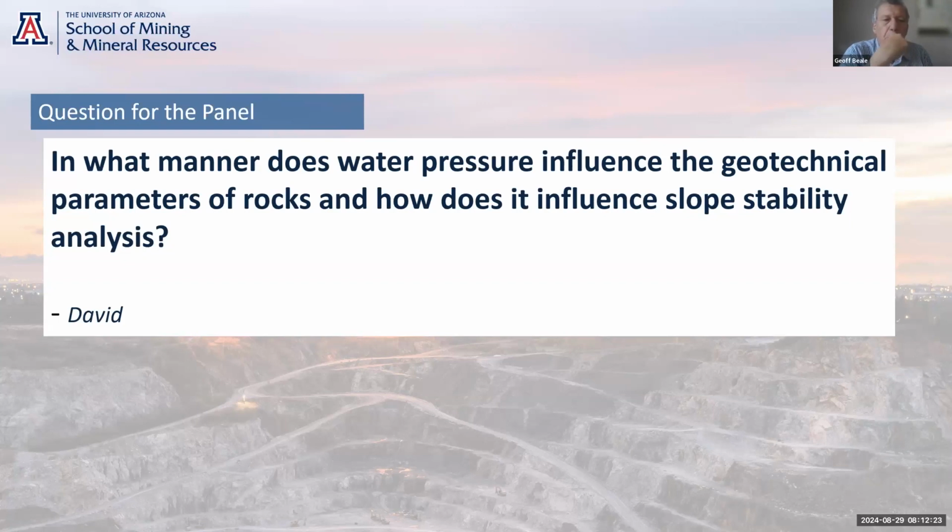As soon as you put a bit of water in, you create an upward force on the top plate of glass, or the upward force on the top surface. And it reduces the effect of the downward weight. So it reduces the effect of the downward stress. So it reduces the effective stress.